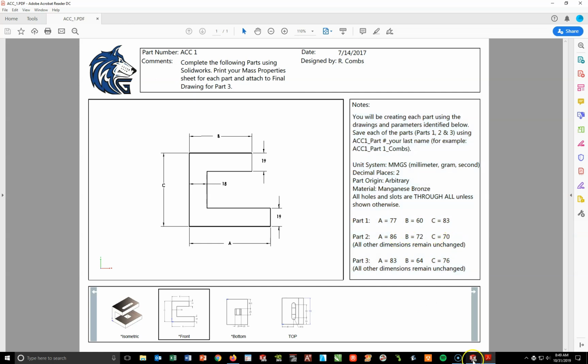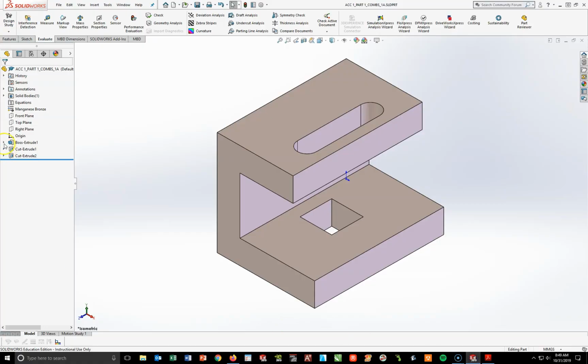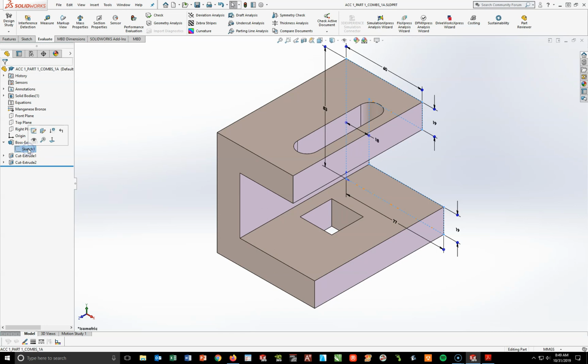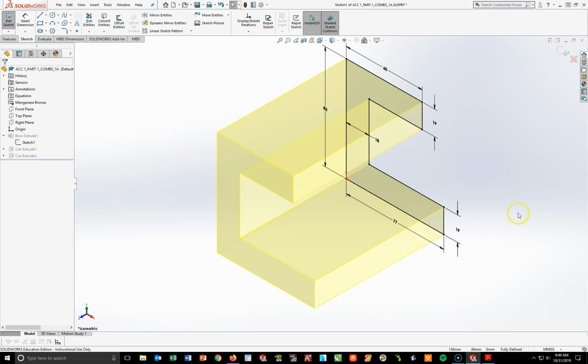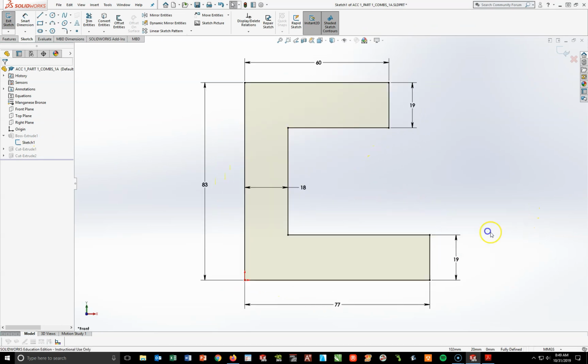So how do I do that? Well, let's go to SOLIDWORKS. Let's go to the very first sketch we have right here. Okay, I'm going to expand this branch so I can see the leaf called Sketch 1. Left click on it, and let's go ahead and edit it right here. Edit Sketch. Do a space bar and a normal to.